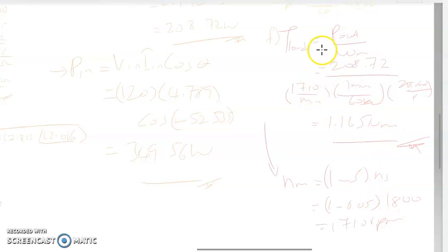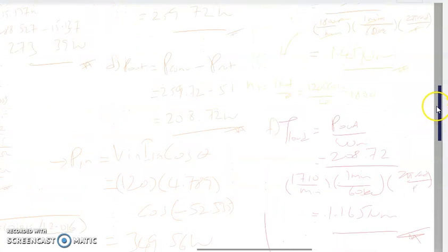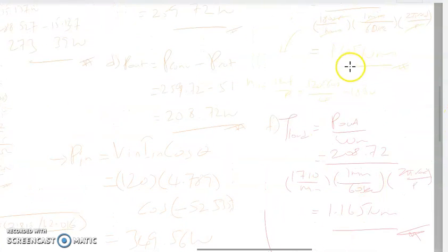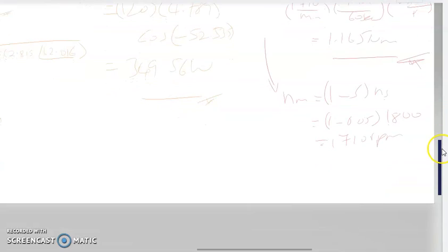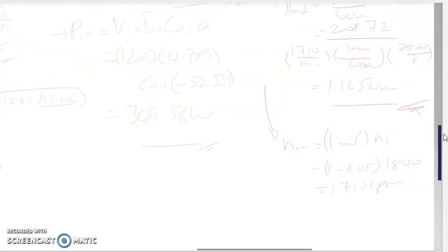So you put it here, and we get the load torque, which is much lesser compared to what is produced at the air gap, because after the air gap we have slip, so we take the slip into account. The remaining torque at the shaft will for sure be lesser than what is produced in the air gap, same as the air gap power compared to the output power. So that's settled for F.